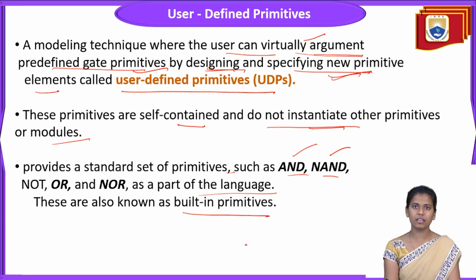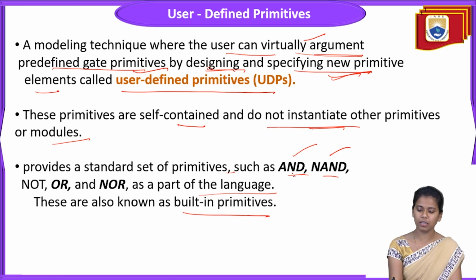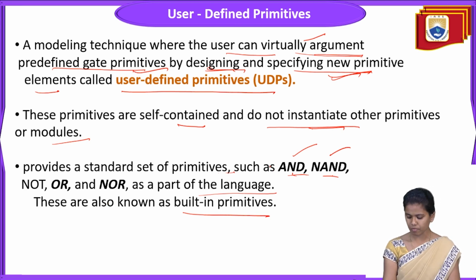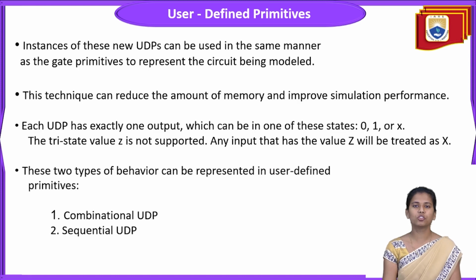As we discussed earlier, Verilog is a case-sensitive language and it has some built-in primitives. Those built-in gate primitives present in Verilog are nothing but AND, NAND, NOT, NOR and OR. These are a part of the Verilog HDL language. I hope you understood what user-defined primitives are.